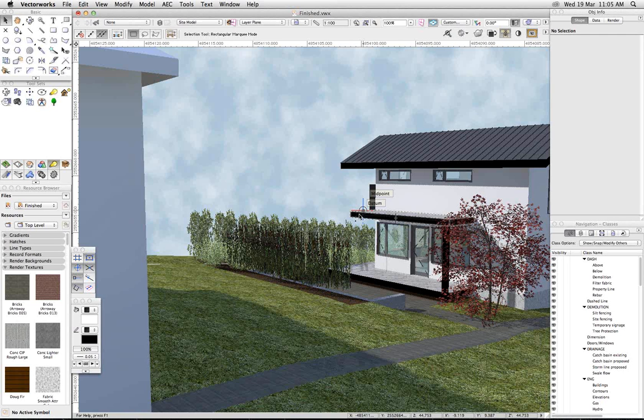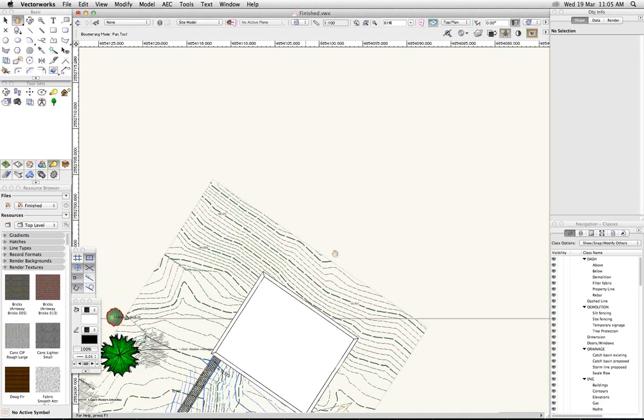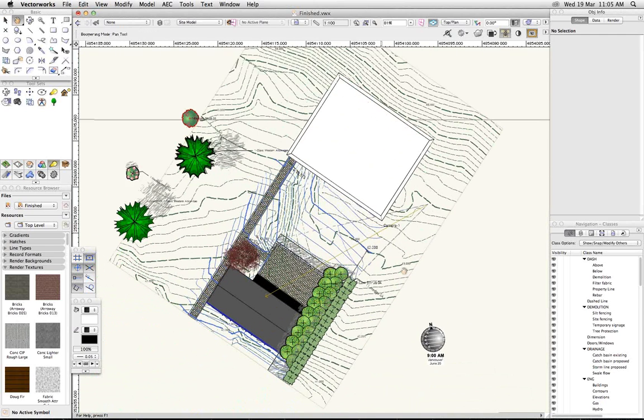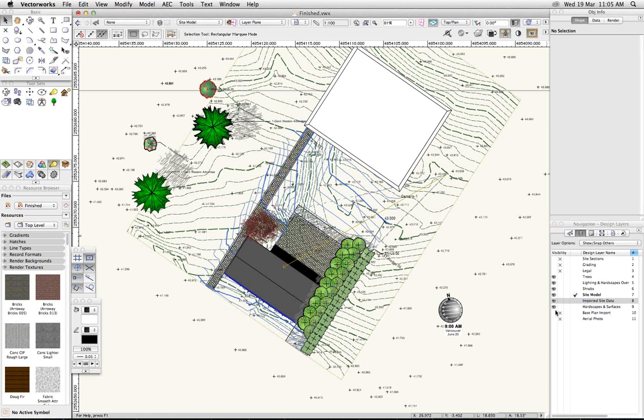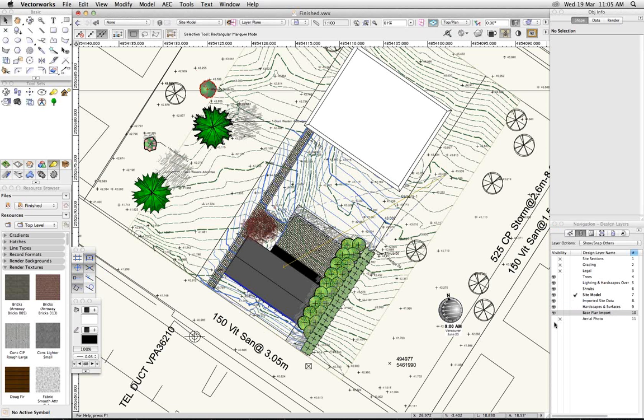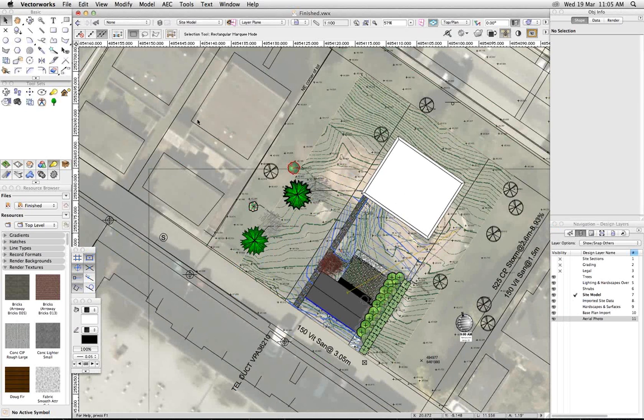The slightly different angle that we'll take today is the import of geo-referenced data, meaning that the XY coordinates correspond to latitude and longitude, and that therefore we can put together surveyor data, base data of property lines and existing buildings and so forth from AutoCAD or DWG files, and air photos.